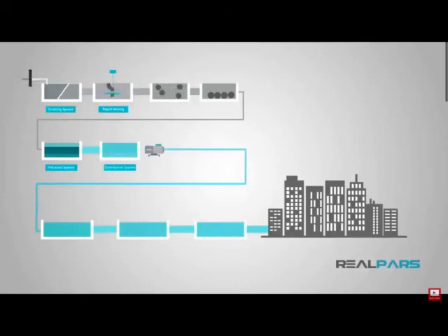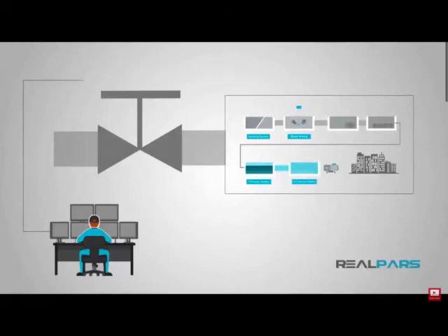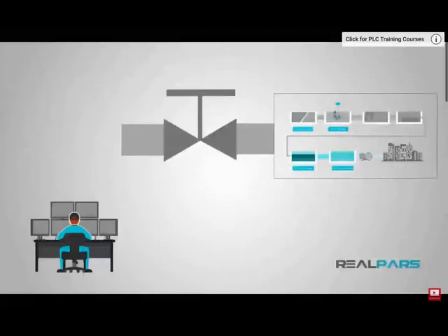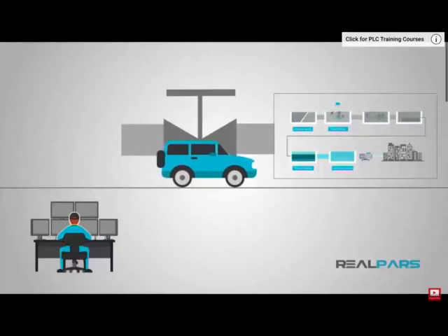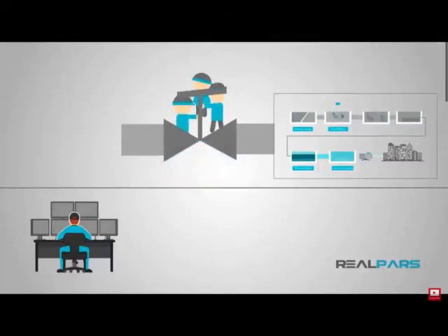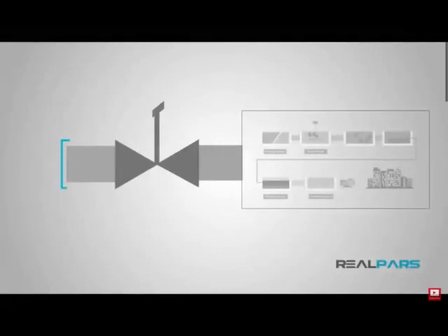They would first have to stop the influent plant flow. This may or may not be easy. If the plant has some motorized valves, they could command those valves to close and begin the shutdown process. If they did not have the motorized valves, the staff would have to travel to the location of the influent valve and manually close the valve. While this may sound relatively easy, some of these valves are on pipes that may be 96 inches in diameter. That indeed would be a very large valve to manually crank until it was fully closed.